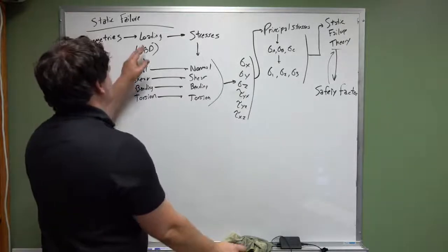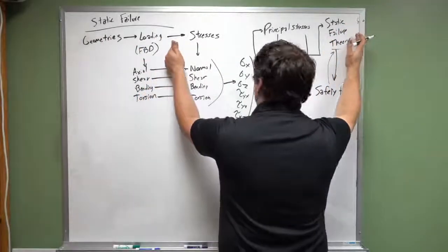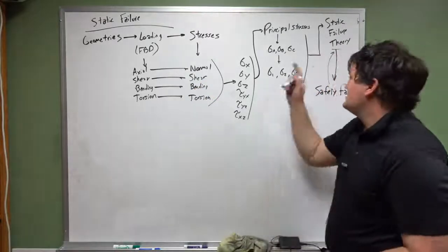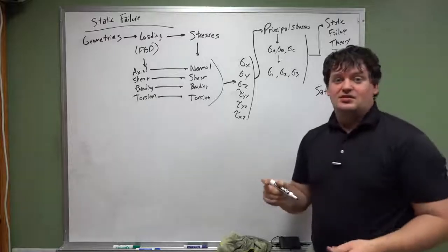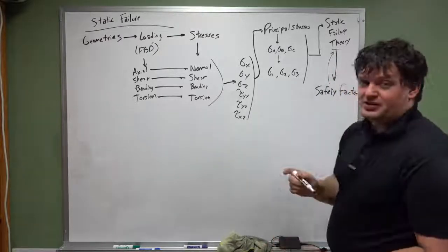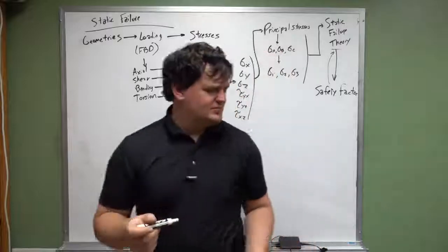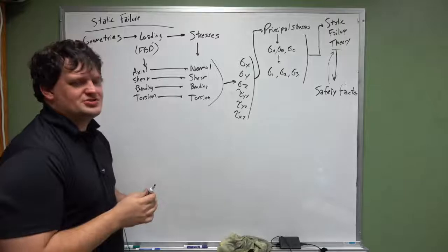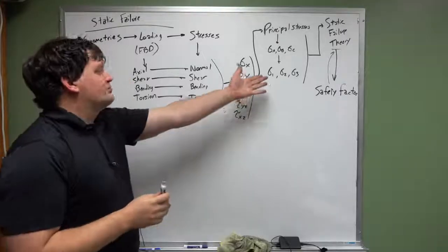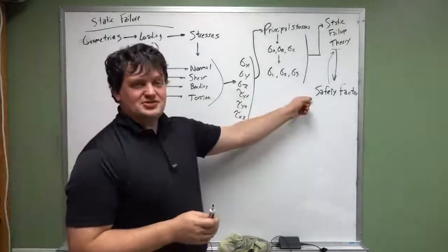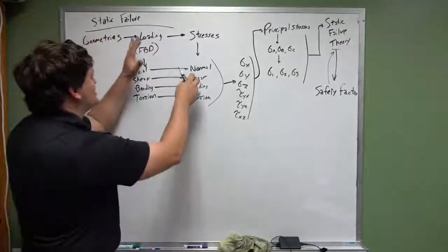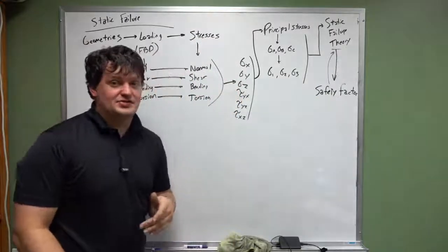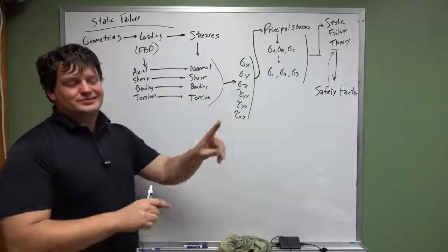If you plug in the geometries and the loading, this part can be done by SolidWorks. It spits out a von Mises stress. Von Mises stress is used in the ductile failure condition. It goes with the DET method, distortion energy theorem method. Okay. Once you figure out the von Mises stress, then you get your safety factor really quick. So as long as you know what these two are, this part can be handled by SolidWorks or by finite element analysis software. That's super awesome.